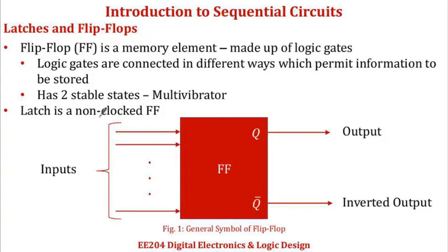Now the most important memory element is called the flip-flop, which is made up of an assembly of logic gates. Even though a logic gate by itself has no storage capability, several logic gates can be connected together in ways that permit information to be stored. There are several different gate arrangements that are used to construct flip-flops in a wide variety of ways, and we shall see them later. A flip-flop is also known as a multi-vibrator because it has got two stable states.